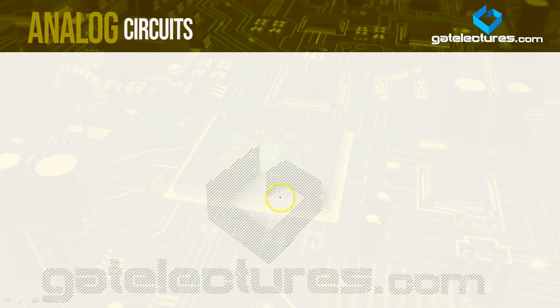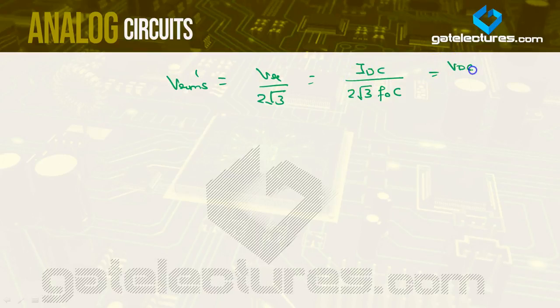Now we know that Vrms prime is equal to VR by 2 root 3. Now we know what VR is. VR is equal to IDC by F naught C. So Vrms prime is IDC by 2 root 3 F naught C. Now what is IDC? We know it is equal to VDC divided by RL. So Vrms prime is VDC divided by RL, 2 root 3 F naught C.